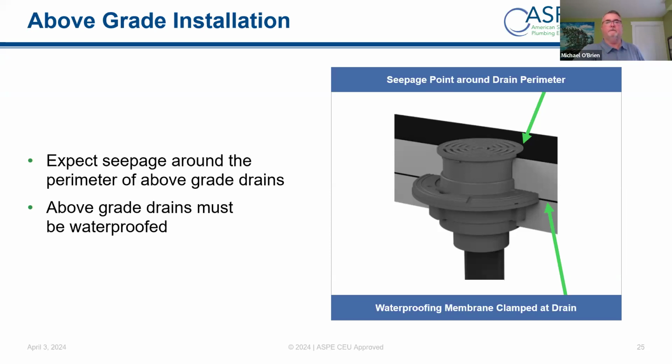So it's relatively easy to do with a drain like this. Typically, any water that hits that membrane and makes it to the drain has weeping holes that put it down in the drain, so it goes down the pipe past the P-trap, etc. So it's a lot more difficult to do with channels, just because of the full length of some of them, running 100 feet or more.